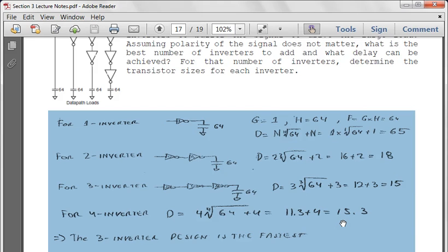So, a common mistake: I'll just do one inverter. I think that's going to have the smallest delay. It doesn't. It also is going to impact your ability to get to noise margins, because it's going to impact the sizing of the transistors. So then what happens? Simulate and tweak, simulate and tweak. Why won't this inverter work? Well, you should probably have 2 more inverters. That'll help. Okay, there you go. Math.